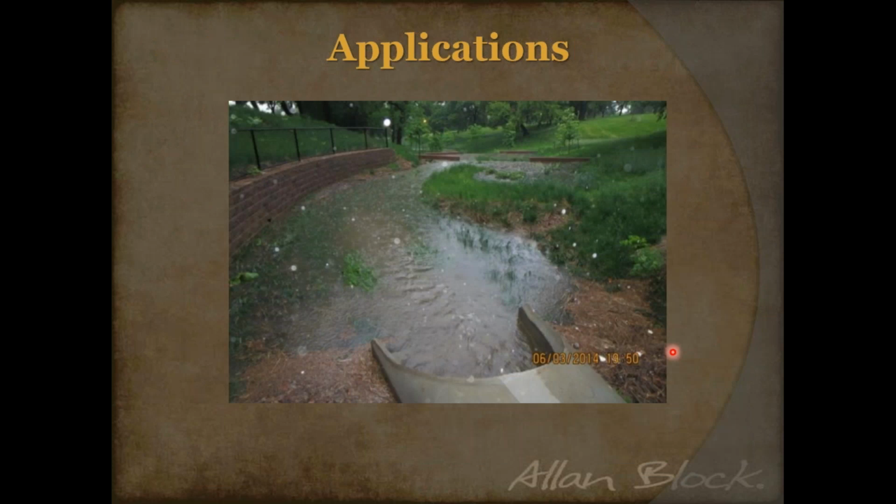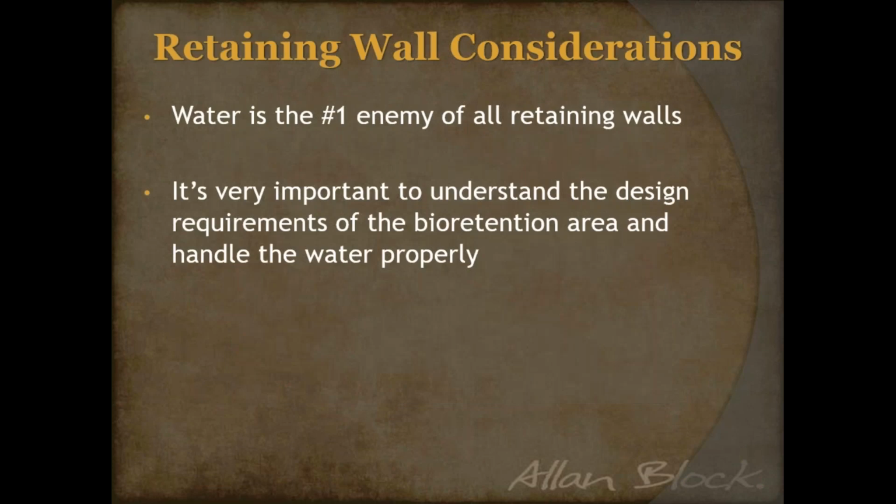Here's another application. You can see it's obviously during a rainstorm, so you've got the slope that would be coming down, and the retaining wall is now holding back that slope, giving you the option to build that bioretention pond here. And obviously in the peak of a storm, you might see some hydrostatic or saturated conditions, even some ponding water here. You can see it's coming up and over a lot of this plantable material, so there could be standing water. And so it always comes back to understanding the water.